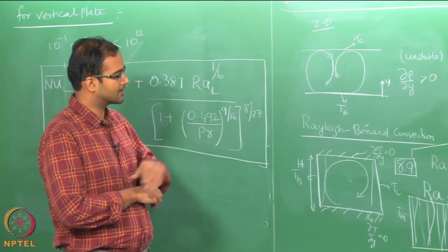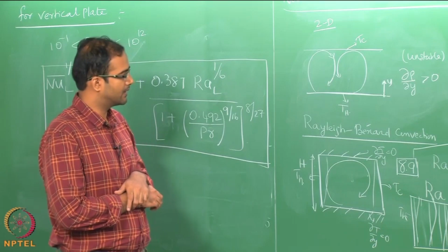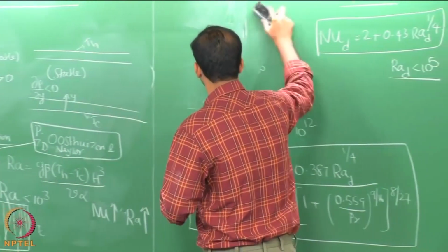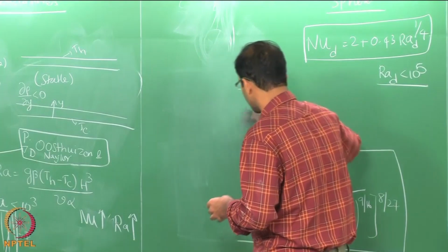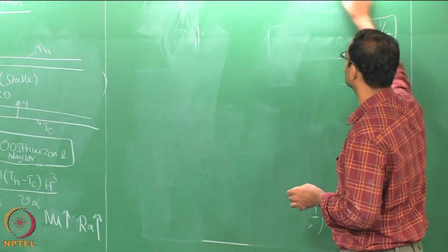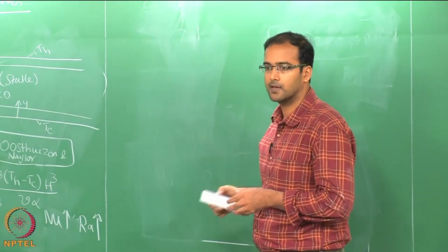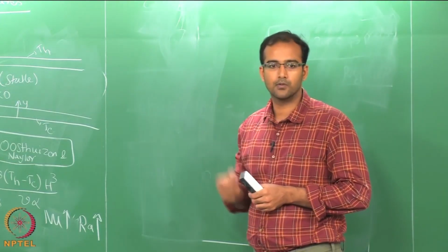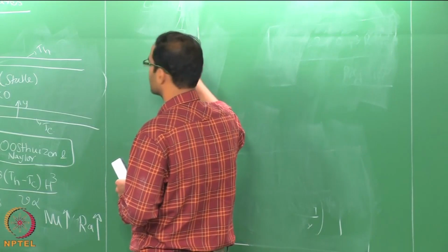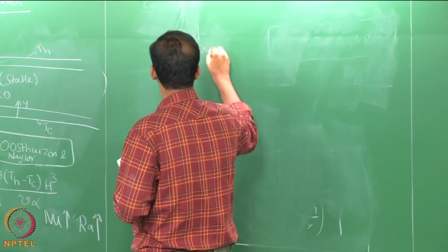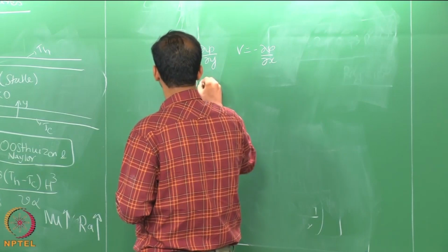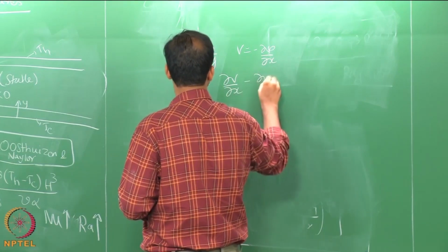Especially look at this section. He has very nicely shown that the way he is solving these equations is by what is called the stream function vorticity method. Rather than directly solving the continuity and the momentum equations, if you use the stream function it makes the continuity equation redundant. Therefore, rather than having so many equations, you have only two equations, one for the stream function, the other for vorticity.